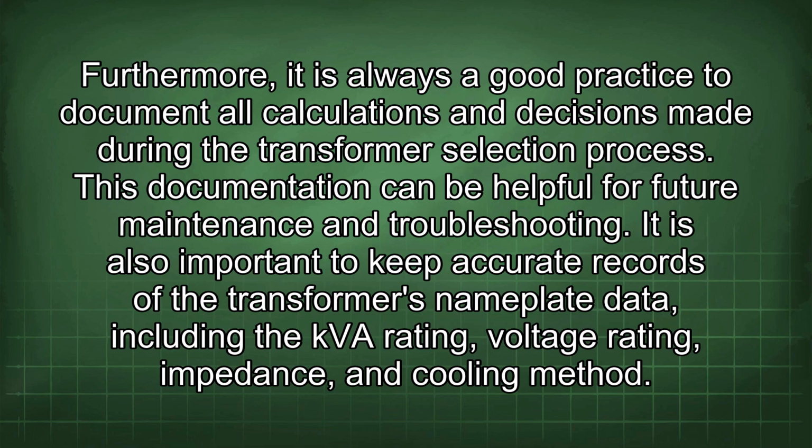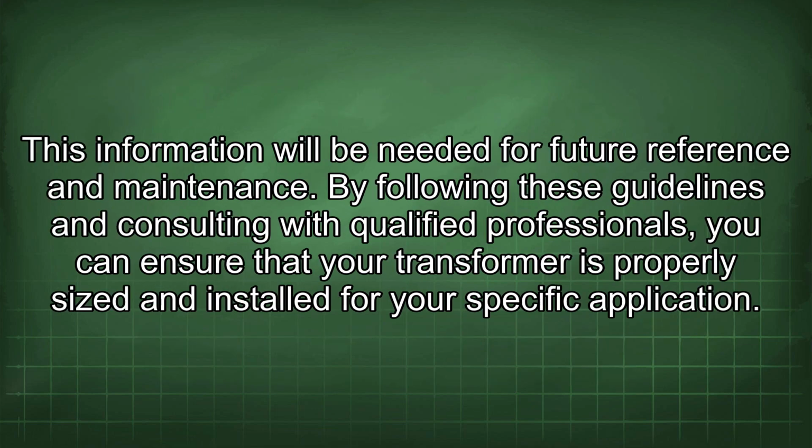This documentation can be helpful for future maintenance and troubleshooting. It is also important to keep accurate records of the transformer's nameplate data, including the kVA rating, voltage rating, impedance, and cooling method. This information will be needed for future reference and maintenance. By following these guidelines and consulting with qualified professionals, you can ensure that your transformer is properly sized and installed for your specific application.